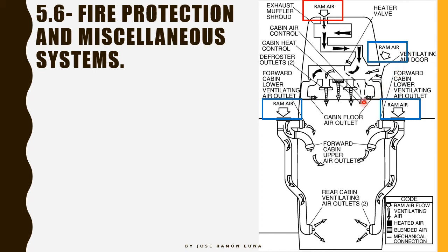That control right here is a push-pull control that you have in order to control the temperature of the flow that is coming inside of the cabin. We have this mixing unit right here, mixing hot air with cold air, depending on the inputs given to the valves. And this is going to tell what the temperature of this outlet air is going to be. Okay, good. So that's for us, that's for the pilots.